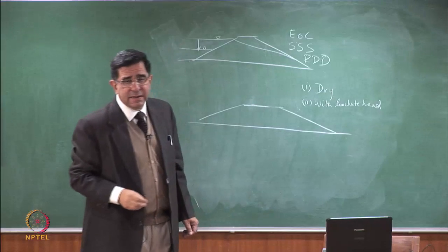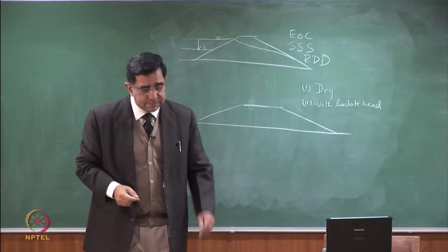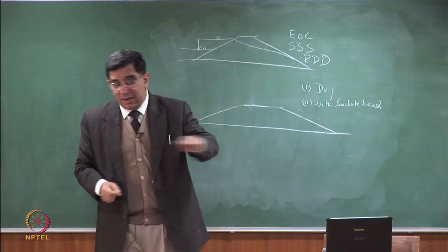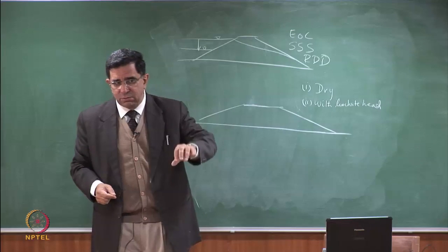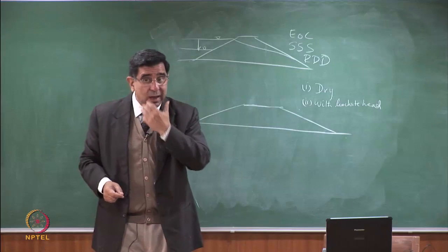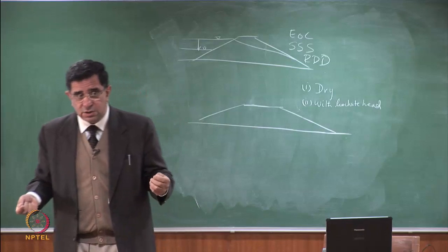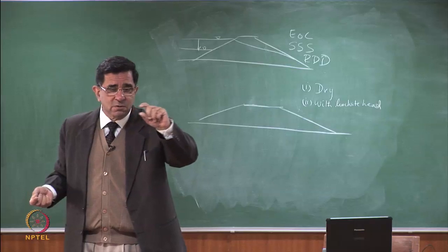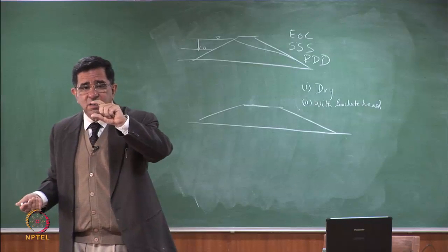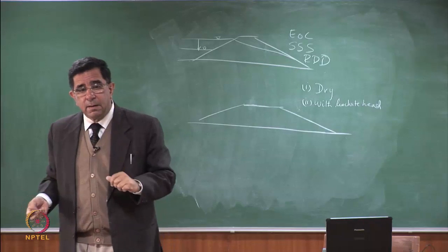See, unlike an embankment, which doesn't have a liner at the bottom, if any rain comes through, it will go down, right? Here we have made a liner and we have got a leachate collection system, so there should normally be no leachate. Maximum head should be 30 centimeters corresponding to the thickness of the leachate collection layer. But what do we have here?